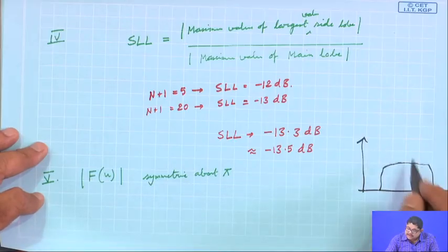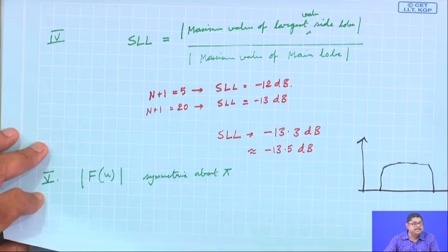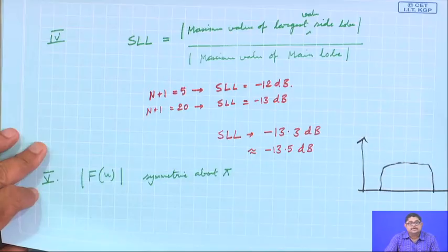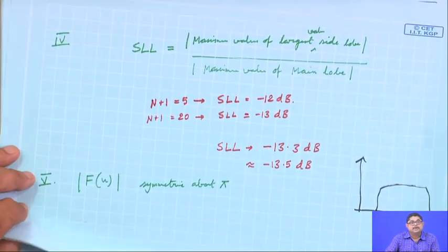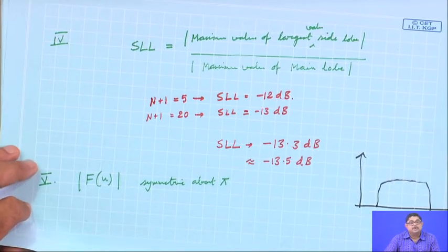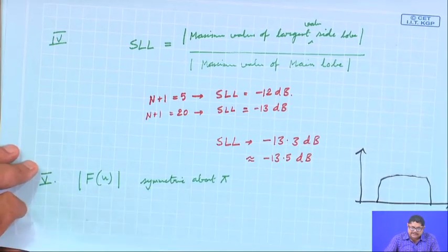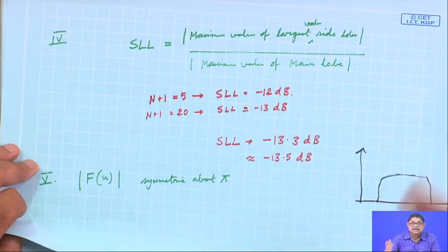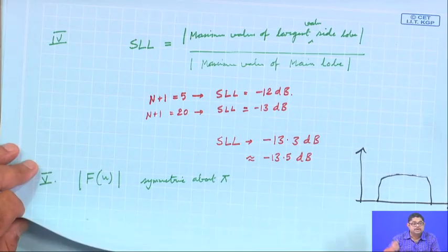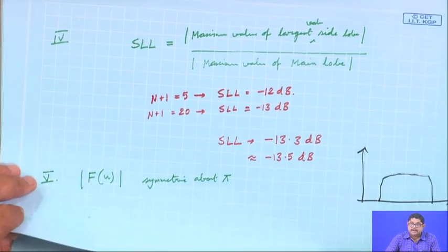Or someone might say that I do not want any side lobe, or I want the side lobes to be very small, and I do not care about the directivity. These things are not possible with a uniform array. Always there will be side lobes, throughout the whole space the beam is extending; it may not be the main beam, but the other beams are always radiating. So, if there is a strong interference from that direction, or strong noise, it will pick that up. So, this is the motivation for going to array pattern synthesis.